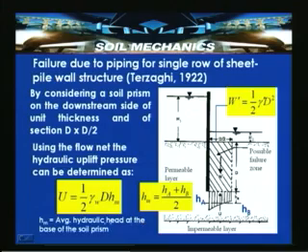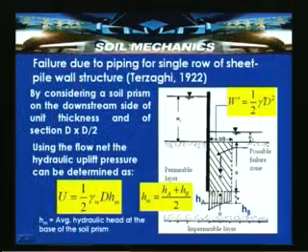So, remember here the average hydraulic head is determined by calculating the total heads at the respective equipotential lines, or the lines approximated to lines which are passing through that particular zone. So, by doing that, this is the prism of soil, the distribution with HA and HB, which is approximated as U, with HM given as (HA plus HB) by 2.